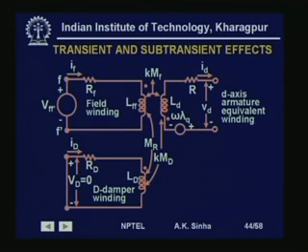One is in which all the 3 circuits are there, since these three will be in parallel. Therefore, the total inductance is much lower, and this is what is happening in the initial part, and this we call the subtransient reactance.